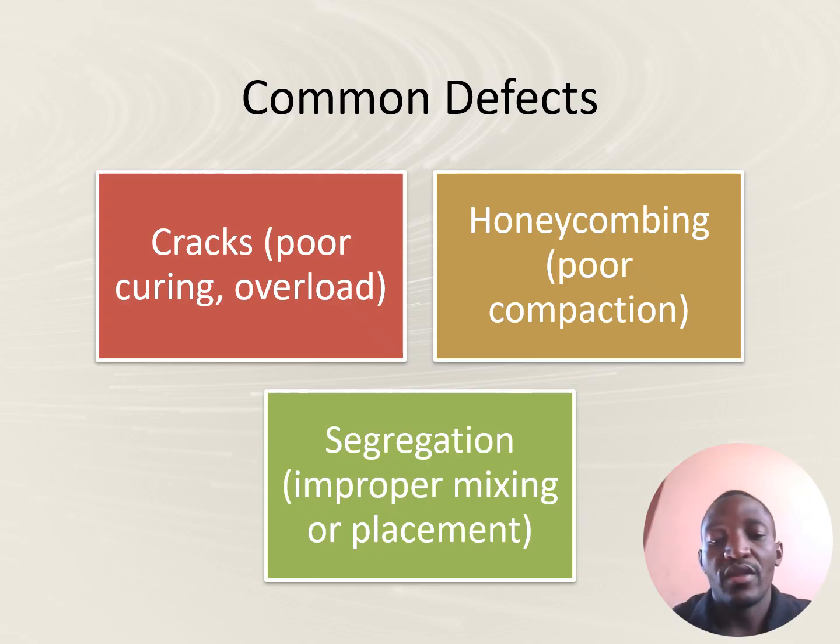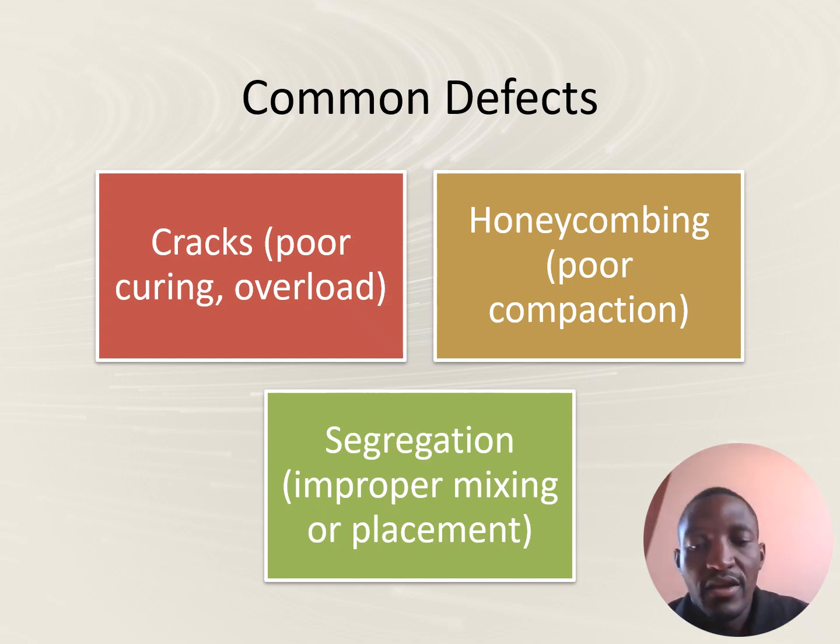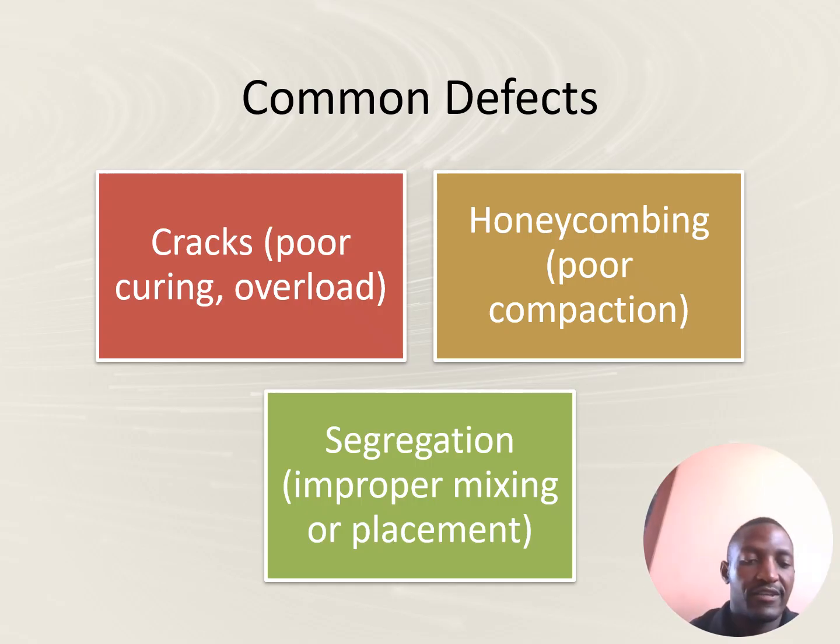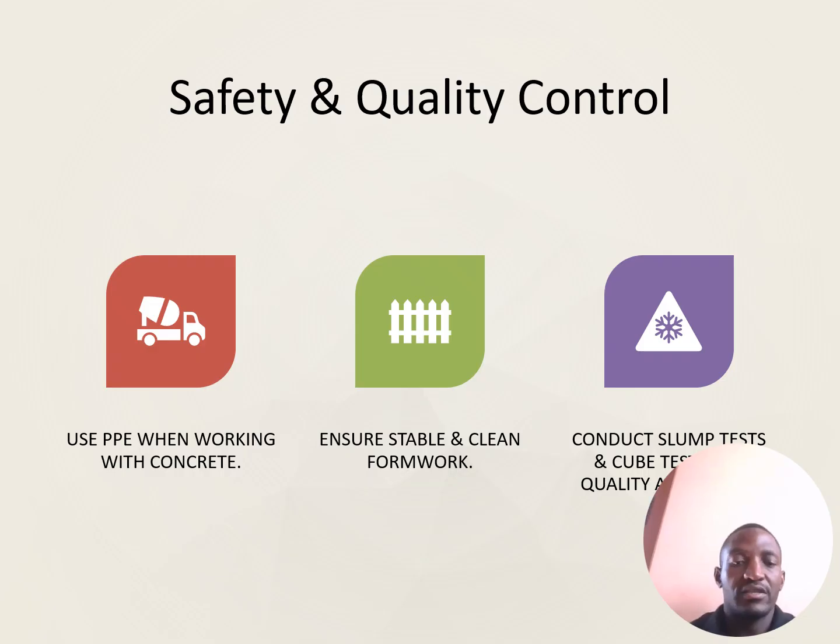If you're not going to mix your concrete properly, you're going to experience segregation. Make sure you do your proper mixing and proper placement. Next, let's look at the next slide.